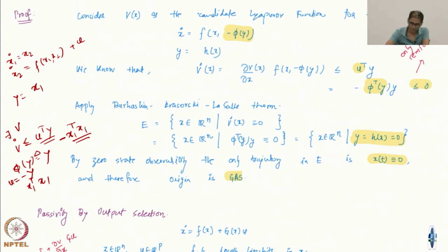You are used to that. For passivity, what I am going to do is, I am not trying to construct a CLF or anything as of now, because we want to use Barbashin-Krasovskii type ideas. So let's see, I will choose my measurement as the position, or the x1 state. If you think of a mechanical system, it is the position state. I just measure one state, x1. What happens? So the question is, can you choose a V appropriately?